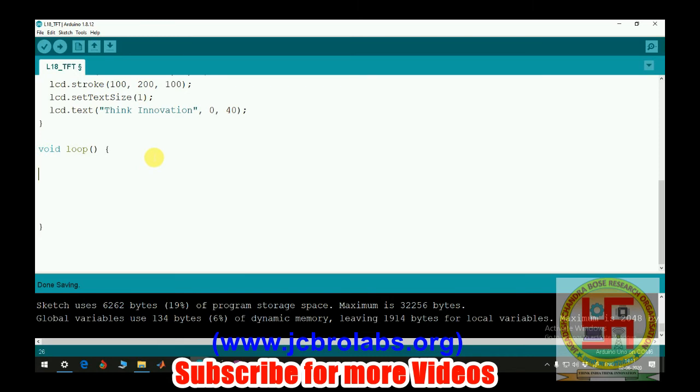We'll read the analog voltage and convert it into a string type. So a string, we are taking the analog voltage, equals String, and then analogRead capital A0, comma 5.0 divided by 1024.0. It will read the analog voltage, convert it into the 0 to 5 range, and then convert it into a string type.